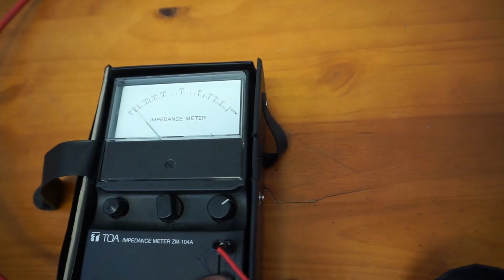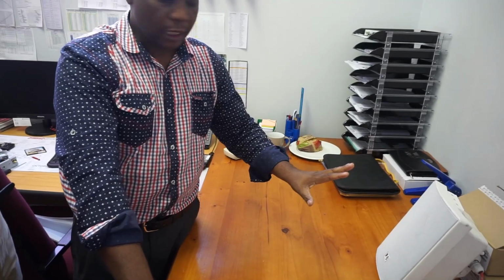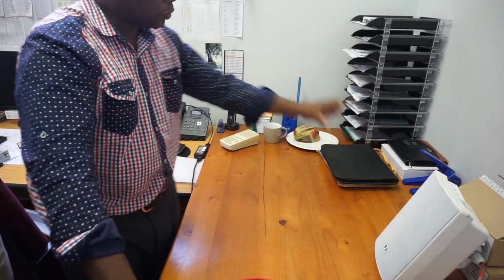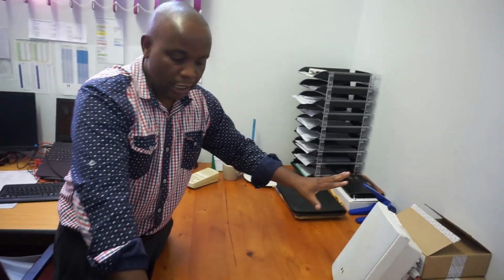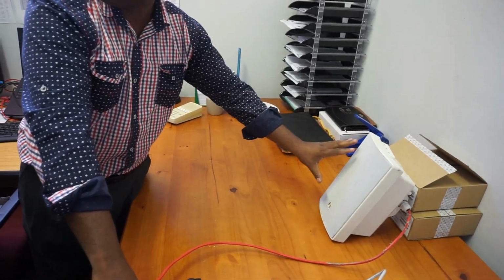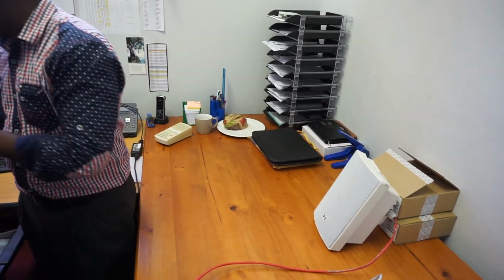when you are doing fault finding on a speaker line, the first thing you do is plug in your impedance meter. You should hear a 1 kilohertz tone playing on all the speakers connected on that line before you even calculate the impedance. This gives you audio to say that speaker is working. Any speaker connected to this line that does not give you that sound is an open circuit. It's not working. So first, connect to a zone, walk through the zone, and hear the 1 kilohertz coming from each and every speaker on that particular zone. Then you are sorted.